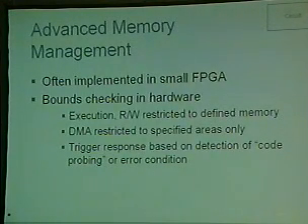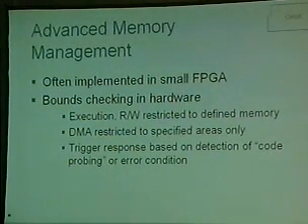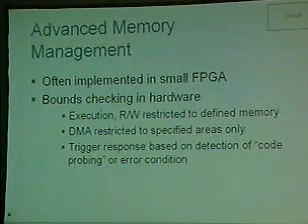Another thing that's nice on more complex systems is to have an advanced memory management unit. What this will do is sit and monitor the address and data lines, and also, at least on the 68340 series Motorola processors, there are 4 bits that determine if the system is running in supervisor, user, or if it's a DMA operation.